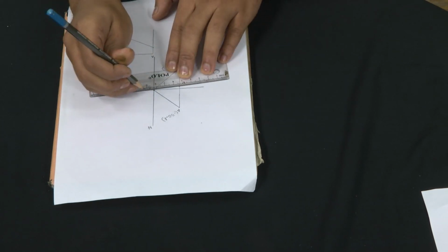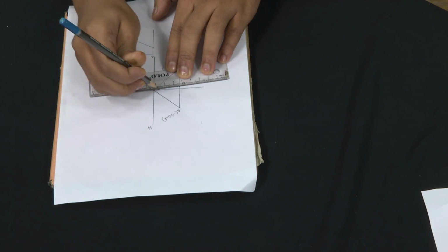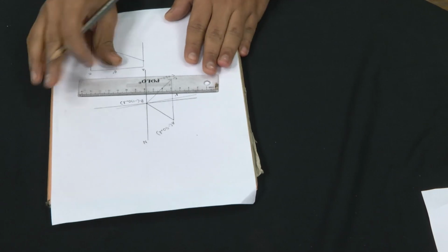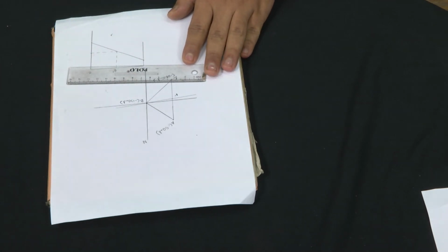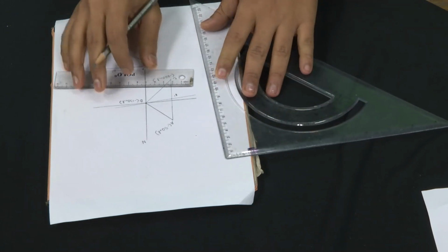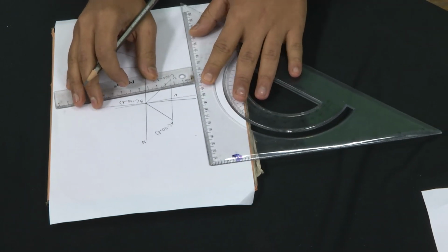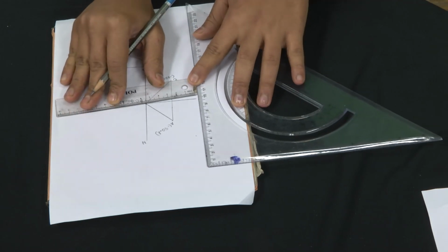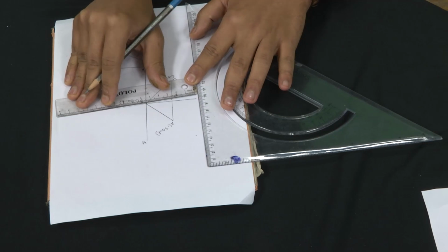First I construct the minus 130 meter strike line, which is this. Now in this problem I construct a strike line parallel to the minus 130 meter strike line from the point A, which will corresponds to the minus 50 meter strike line.